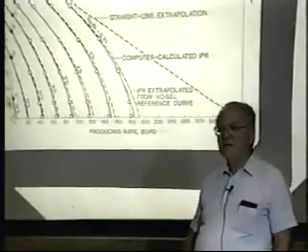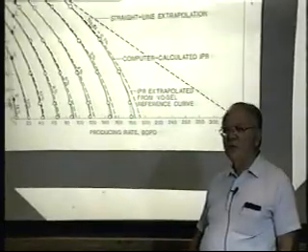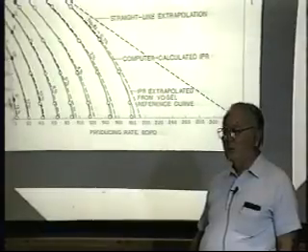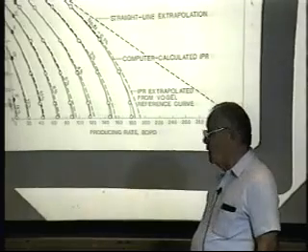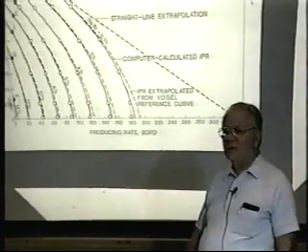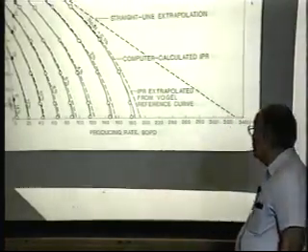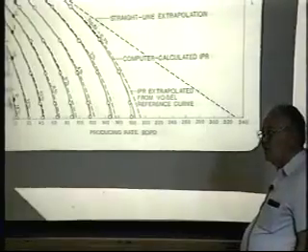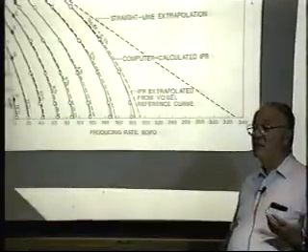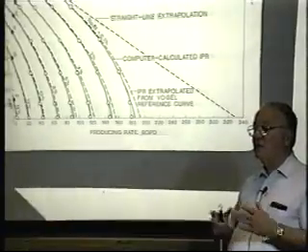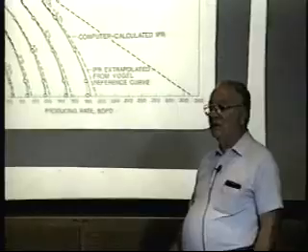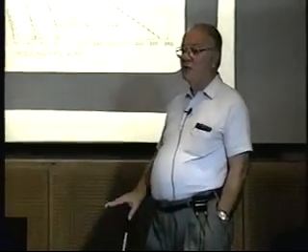Q over Q max is equal to 1 minus 0.2 the ratio of Pwf over Pr bar, minus 0.8 times the ratio of Pwf over Pr bar, that expression squared. When he presented it in dimensionless form, and being in the gas department, we had a dimensionless form of the back pressure equation that we used to size orifice plates when we were running multipoint tests. And when I saw his paper, immediately it became apparent to me that what he's saying is that oil wells should behave just like gas wells.